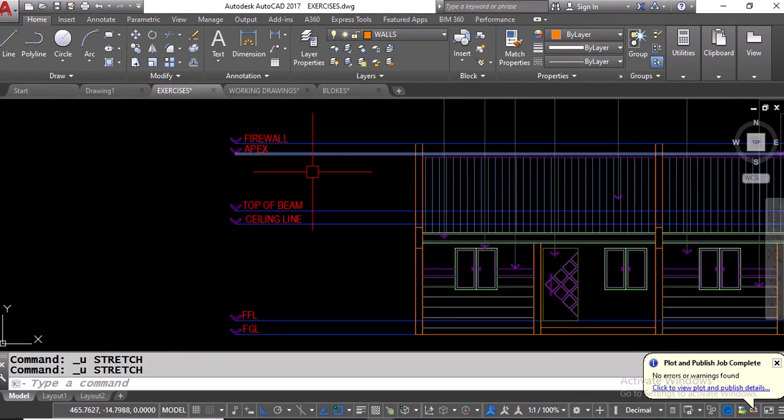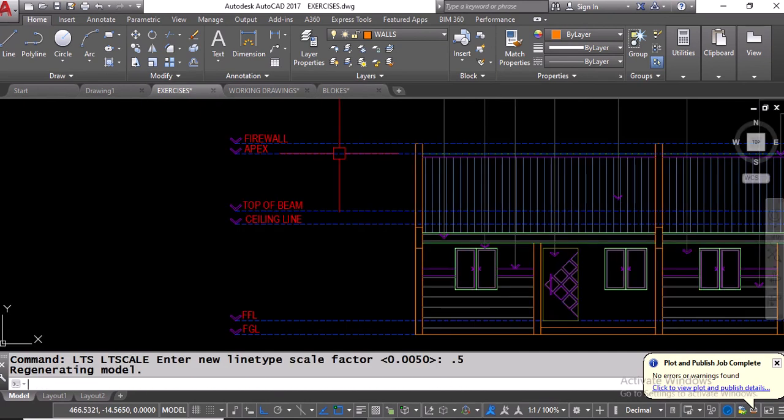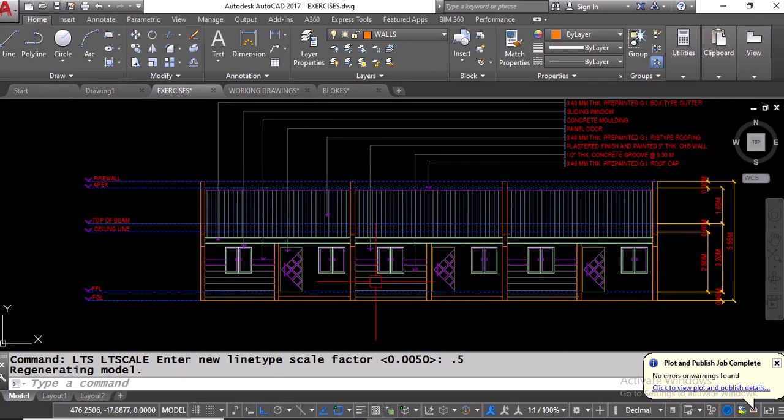And of course, as you can see, balik tayo sa model. Technically, you have to adjust your line type scale ulit by 0.5 or paki-check. Meron kasi mga drawing files na minsan hindi 0.5. Minsan 0.1, minsan 0.1 or minsan 5 talaga. Okay? So, please check the line type scale always for your line type. Again, magkaiba po si model, magkaiba si layout. You have to adjust every now and then na naglilipat ka. Okay? Anyway, so, I did this one. And then, of course, just copy.